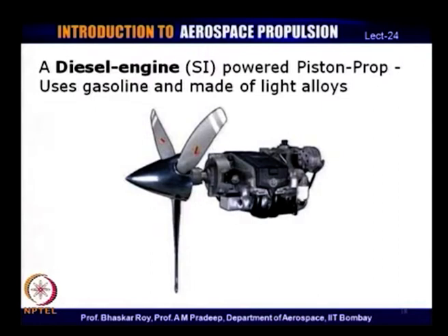However, very recently some people have started looking at the diesel engine, simply because of the thermodynamic consideration that we have talked about, that a diesel engine has intrinsically more thermal efficiency, and that is something which has triggered recent research in which people have tried to design a diesel engine that is light, made of light alloys, and uses the normal aircraft variety of gasoline, and it can be used to power a propeller.